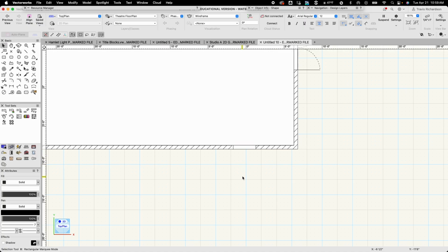And then I need to draw my door and the arc of the swing of that door as well. So I'll activate my line tool. This is the hinge point, the bottom right-hand corner. And so I'll select that, and I know that this is going to be 3 feet because that's how wide my door is. So I'll tab in, 3 feet. There's my door, and I need to draw that arc, so I'll select the arc tool, still in radius mode.